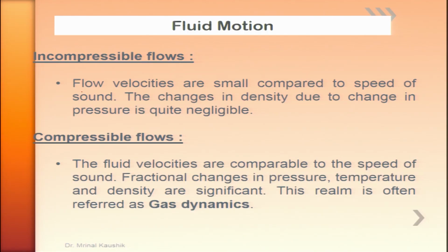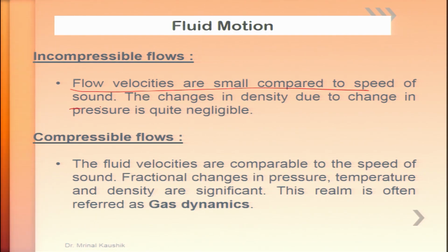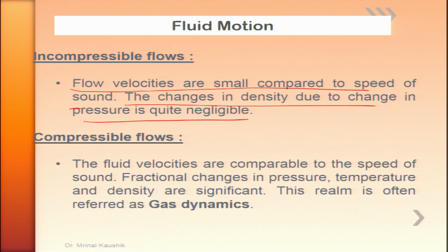Now, in our discussion, in an incompressible flow, the flow velocities are very small compared to the speed of sound, and the changes due to the change in pressure are quite negligible. That is, even though an acoustic wave is traveling, it is not incorporating much change in pressure and density. Whereas in compressible flow, whenever the waves travel, the pressure and density changes are finite and should not be ignored, and we must include them in the